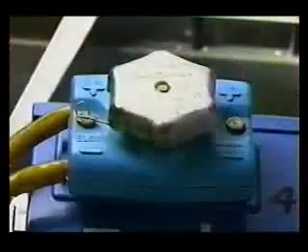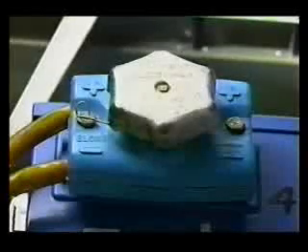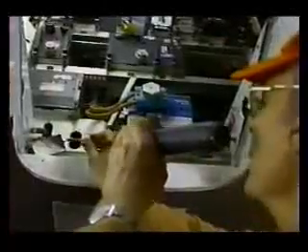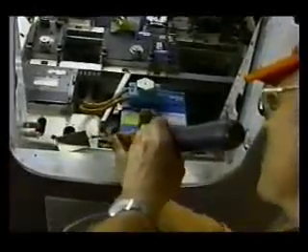As discussed earlier, aircraft batteries use an electrochemical process to generate energy, and this requires an electrolyte. Fumes from an overheated battery are difficult to contain and will spread to the internal structure, attacking any unprotected surfaces. Frequent cleaning of the battery compartment and neutralization of the electrolyte will minimize corrosion.